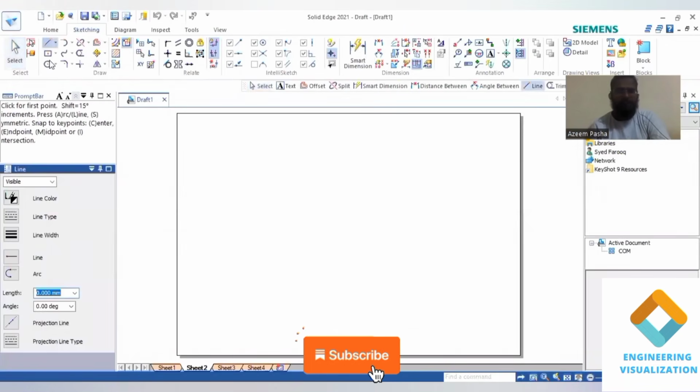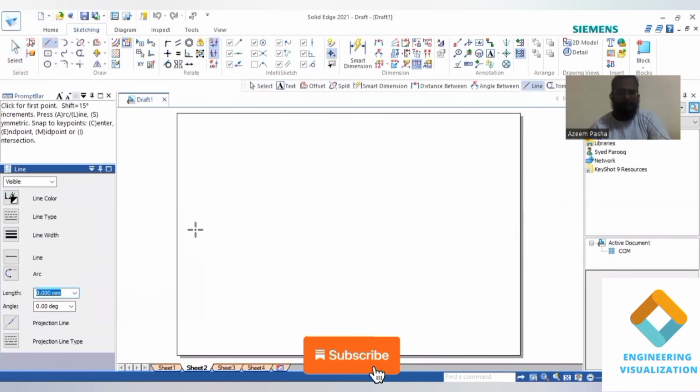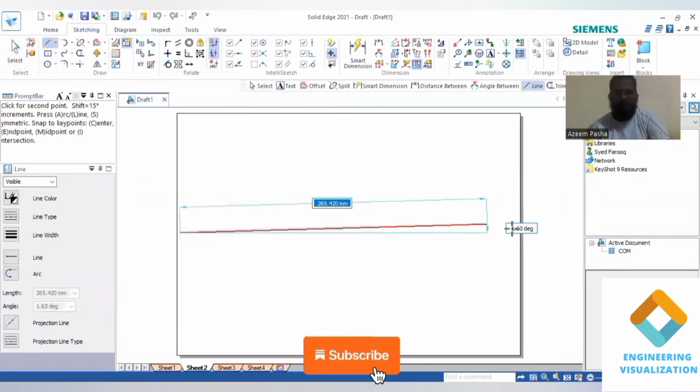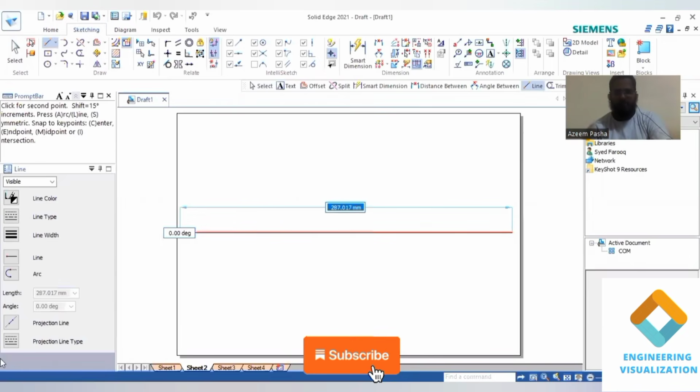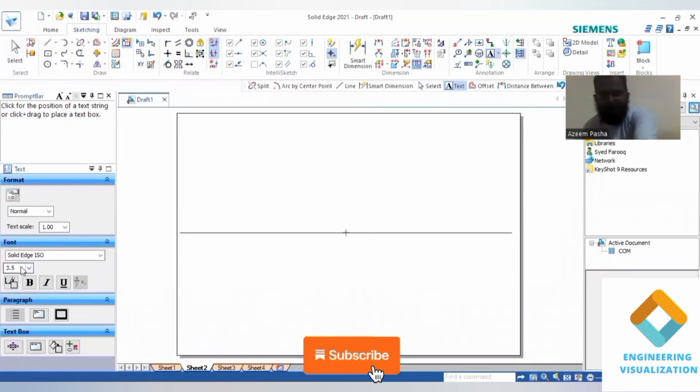So first we will be constructing an XY line. Here for the XY line you can take the thickness either 0.25 or 0.13, no problem. Then you can mention XY line, VP and HP, because it is in the first quadrant. Write XY and VP, HP because this is in the first quadrant. So in the development also we are using the first quadrant only.